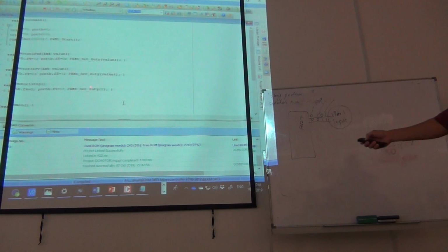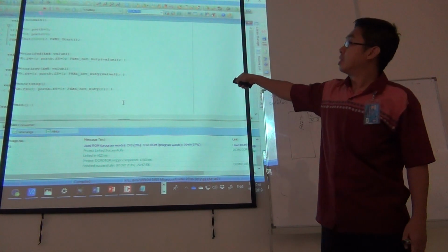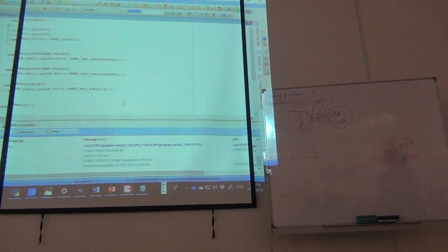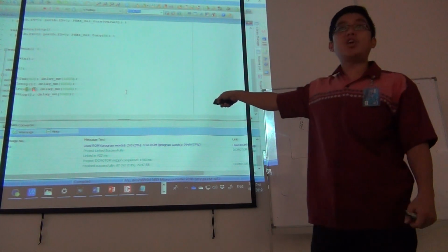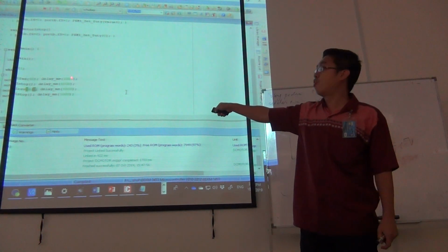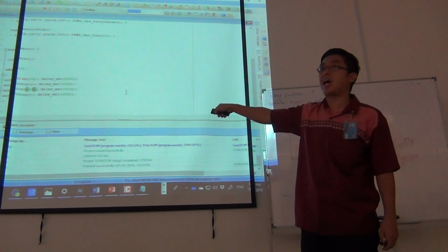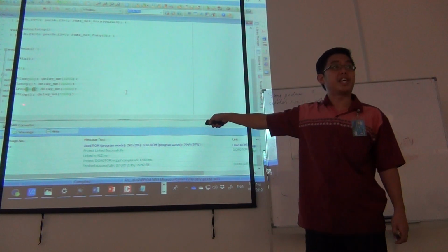My code to run a motor is this one. The main over here is to go forward at 60 over 255, which is the PWM, and delay for 1 second. I stop it and I move in another direction, and then delay, stop it again.